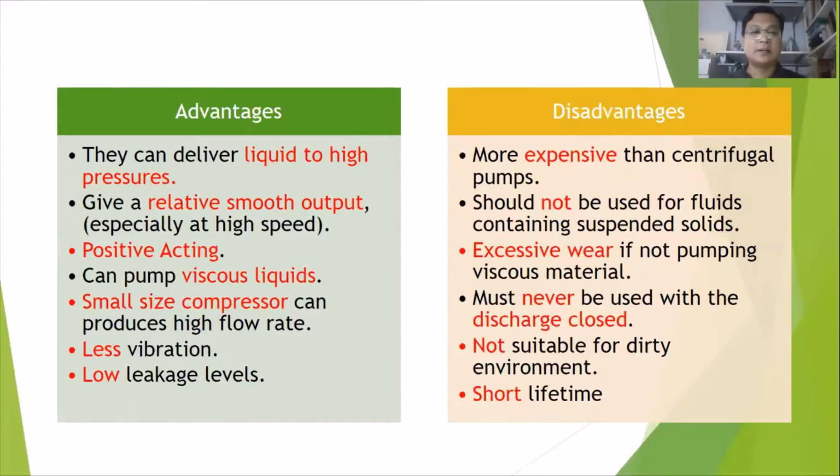But they also have a lot of disadvantages: more expensive, should not be used for fluid containing suspended solids, excessive wear if not pumping viscous material, so should be using viscous material. If not, there will be high wear inside the pump. Must never be used with the discharge closed, not suitable for dirty environments, and short lifetime, very short lifetime.